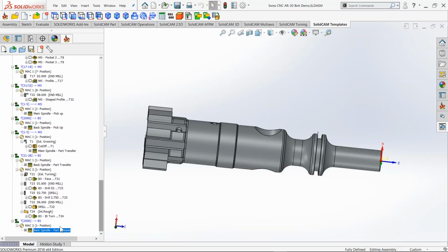As Daniel is going through it, I see Ronnie's eyes getting wide, like, oh man, this looks complex. But like I said, it's no different than doing a standard mill turn, except we have a couple of MCOs in there. And Daniel's going to go over the channel sync. But the main thing we've changed to support Swiss is more on our end versus on the machine end. What I mean by that is the post processor side, to make sure the post is outputting the correct parameters and can work with all the different axes. So, sorry, Daniel.